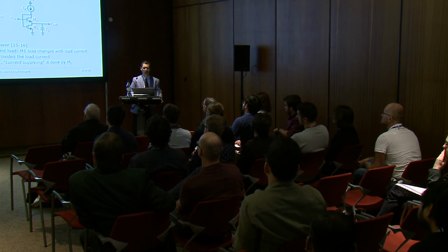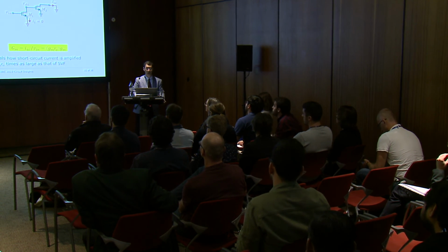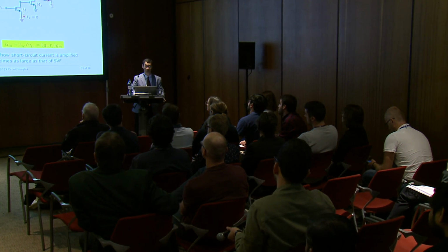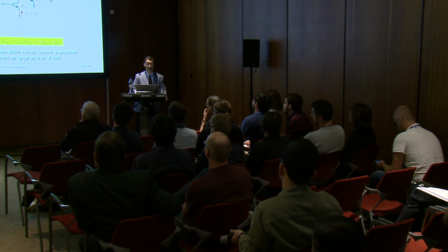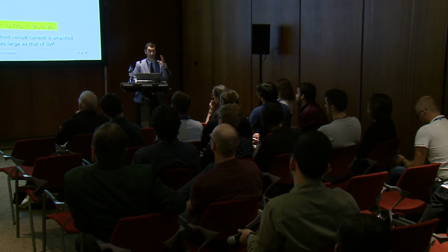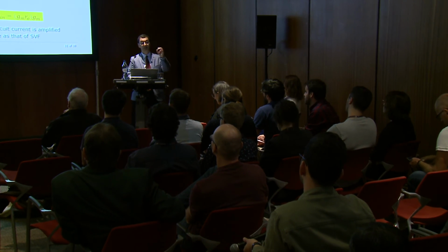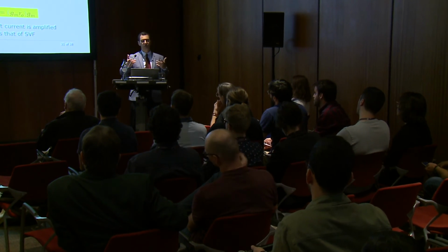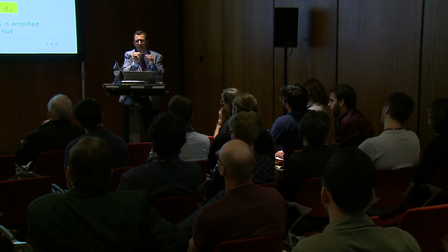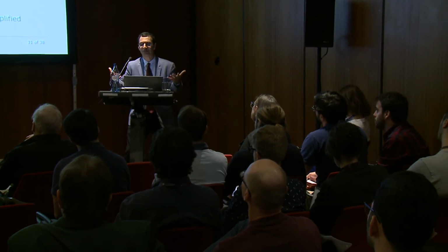Okay. So first of all, the reason why I eliminated this current source at the top was not an approximation. That is exactly how you should do this if you want to analyze a circuit for small signal analysis. You get rid of the DC sources, and that was a DC source. But maybe what you're implying is that I assume it is an ideal source. You don't have to assume it's an ideal source. You can imagine that there's a resistance that only makes things a little bit different, but I didn't want to include it, those are unnecessary for understanding.